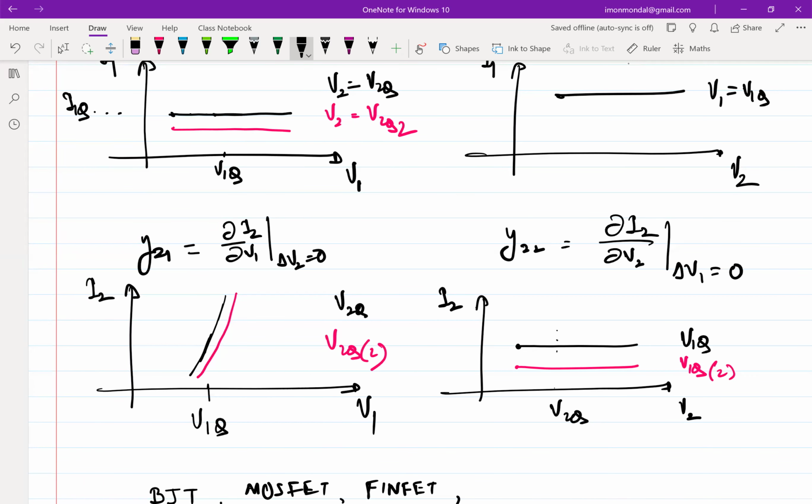Right? When I am doing a differential, I am simply saying I am drawing a tangent. And also I have shifted the axis there. Then and only then it will pass through the origin. So that's what essentially happens. When you do a small signal analysis, we not only draw a tangent, we also inherently make the assumption that in the incremental domain, the moment you go incremental, you are putting the origin around the operating point. If we approach these analyses from the perspective of coordinate geometry, that's what we do. But we don't want to approach it in that manner. But very good question.